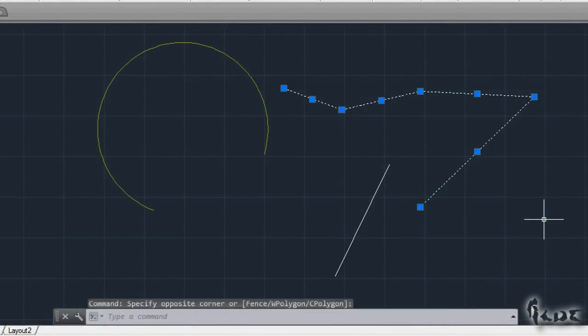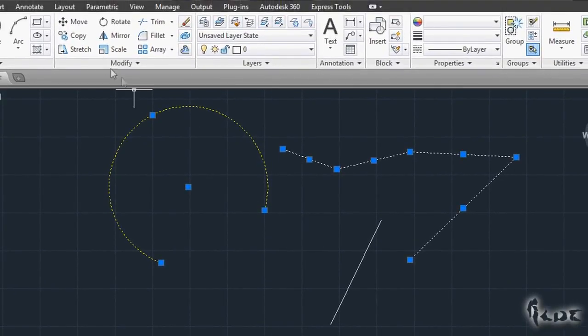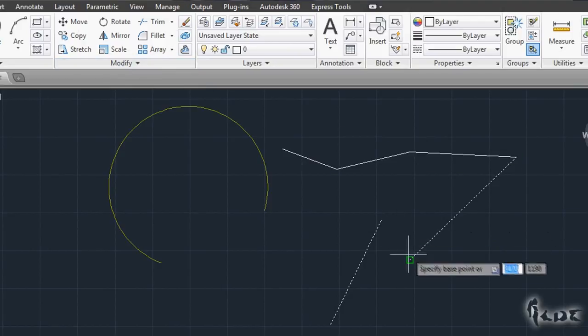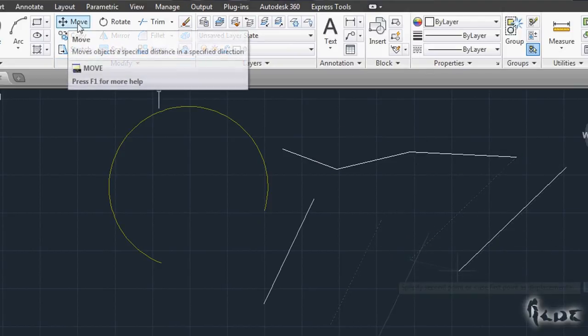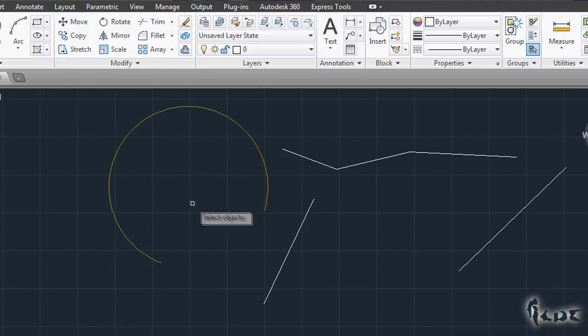There are tools to edit your objects properly, just go above in the Modify section. If you have already selected the objects, you can go on with your transformation. Otherwise, the software will ask you to select the objects first, and the pointer will turn into a small white square. After you made this first step, press Enter from your keyboard to go on with the editing.